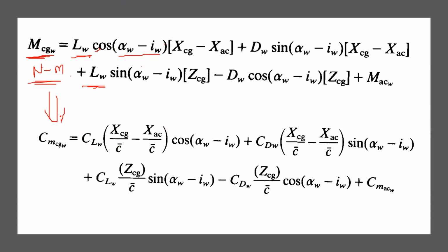Sir, we will take some assumptions like alpha. No. This is an exact transformation. We're not taking assumptions right here. Dividing by Q infinity, C bar. Yeah, what is that? Half rho V square C bar. Right. Anyone else wants to answer and wants to confirm that this is the right answer or wrong answer? Divide by dynamic pressure. Rohan has also confirmed that it is dynamic pressure. Right. So why dynamic pressure?